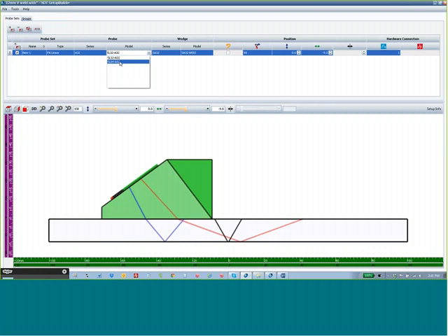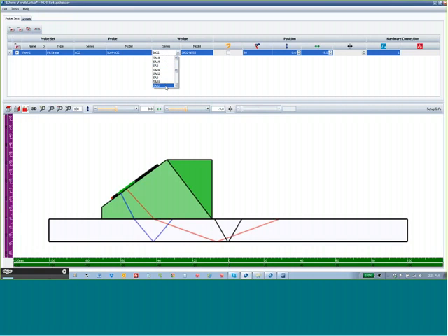We're using the 5L64 version of that probe, which is a 0.5 millimeter pitch, 64 element probe. And we'll do the same for the wedge. Fewer probes using the common wedge family allows us a wider range of inspection without more hardware. And we're using the nominal 55-degree shear wedge in the I8C option for the scanner.